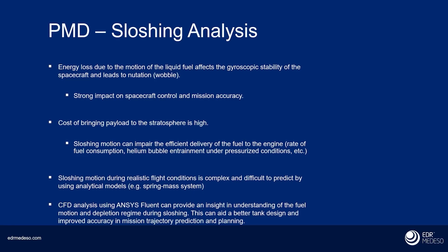So CFD using Ansys Fluent can provide that insight. All we need to do is to provide the representative operating conditions. Once you've done that, then you can get the entire operating cycle of a propellant tank, all of the forces, pressures, and so forth. And that's just going to lead to a better tank design.